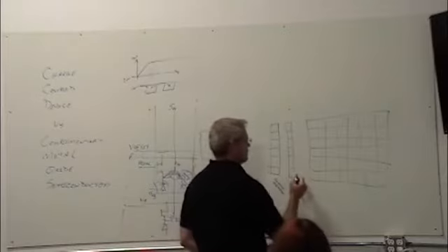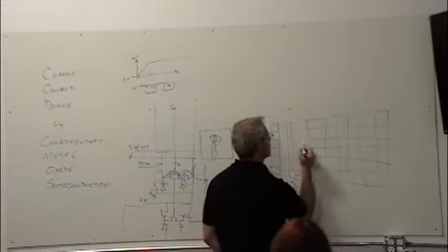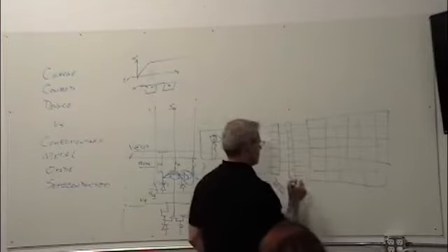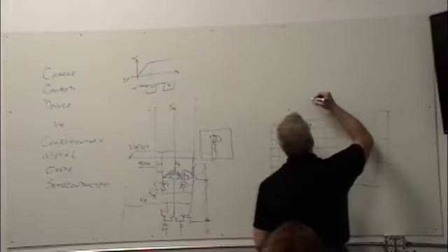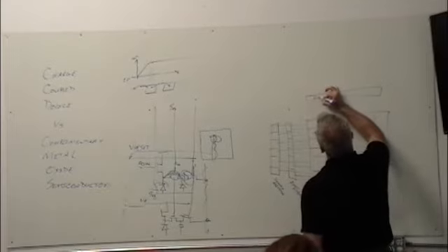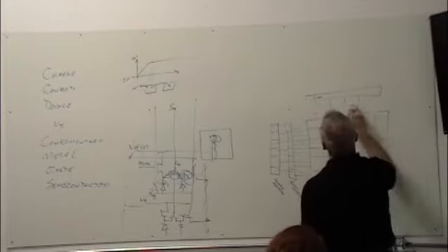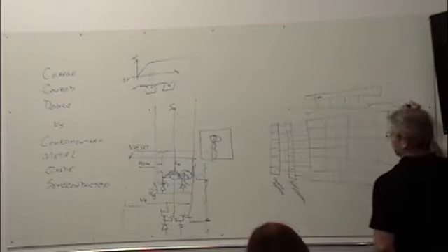This is what you'll see more times than not. And then I'll have another register up here. It's my horizontal select. It goes to the multiplexer here. It lets me do a final readout to wherever it's going to go.